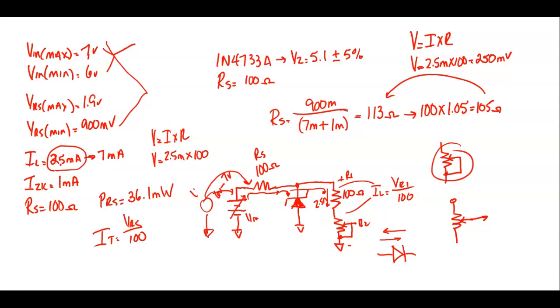Now I've got two options. I could put my meter on amps, break my circuit, and use an amp meter, but I don't have to do that because I've got a resistor. Not only do I have a resistor, I have a 100 ohm resistor, which is pretty neat, right? So what we did is I said, okay, I'm trying to set my load current to get 2.5 milliamps going through my load. So what are we doing? I'm going to do voltage.